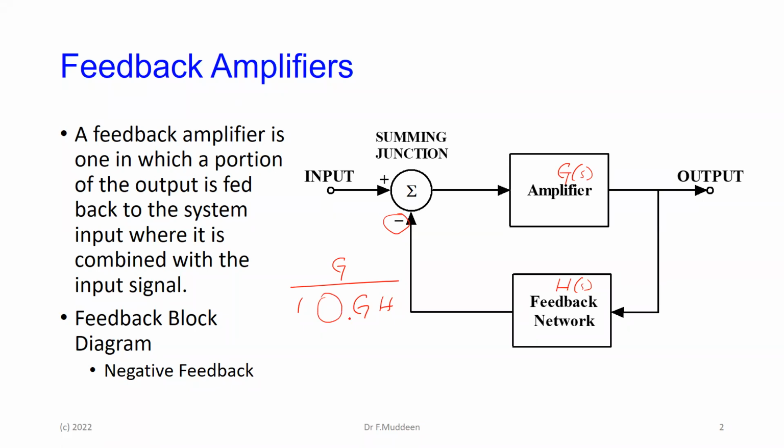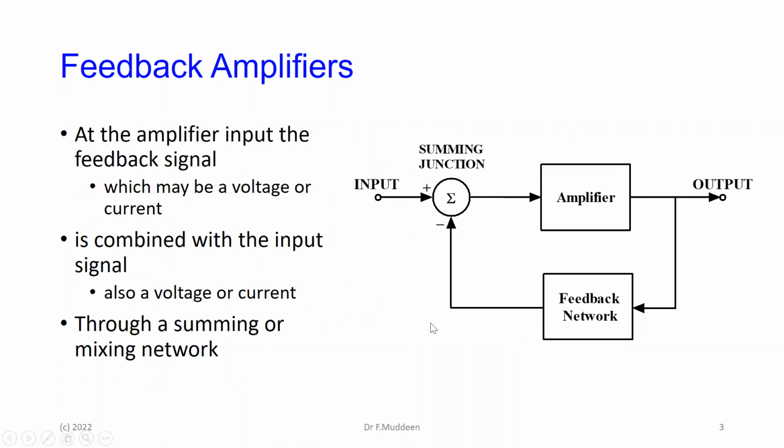And the sign here, was it a plus or a minus? It is negative feedback, so what sign is going to go inside of here? Plus. A plus, right? So for negative feedback, if you have a block diagram of this nature for an amplifier that happens to have feedback, the overall transfer function, in other words, output over input, is going to be G divided by 1 plus GH. These would be the circuits that are composed of operational amplifiers, transistors, field effect transistors, and the like. The feedback network could be transistors or just a passive network composed of resistors and so on.